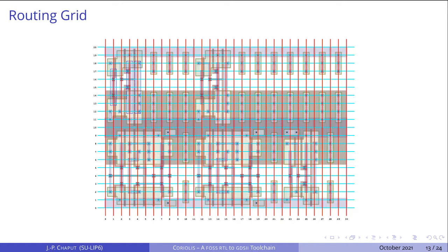So this is also another reason why you may have to expand your placement area, because there is not enough space to make the routing. And that is highly dependent on the kind of design you are making. Some designs do not require a lot of wire and can be placed with a low spacing factor, but others may need a bigger one.